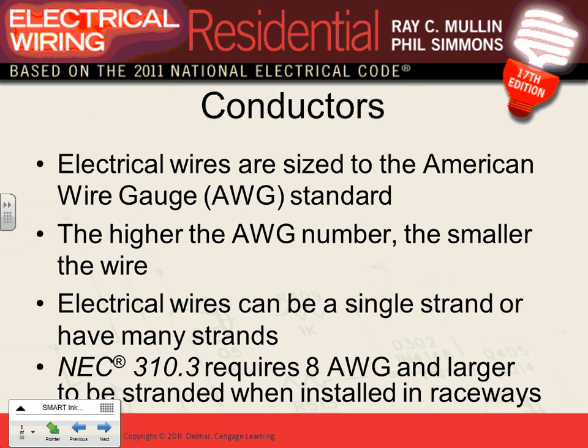So you're going to find I grew up wiring 1.5 and 2.5 and 6 millimeters squared. So everybody knows that one. If anybody is getting into a project where you have to do the metric system, let me know. There's a lot of tables that take you from AWG into the metric system. Tons of really nice tables that get you there. Everybody knows, guys, the higher the AWG, the smaller the conductor in terms of size.